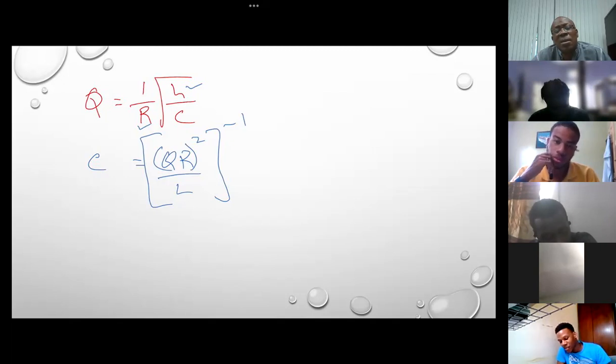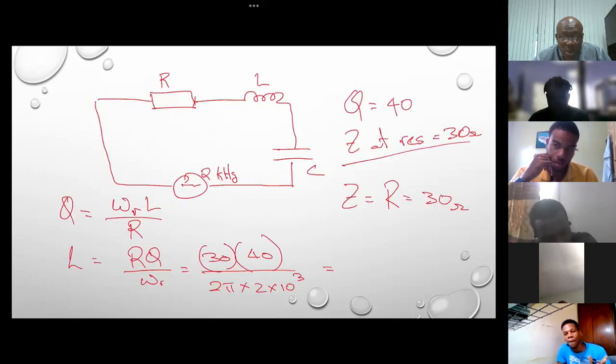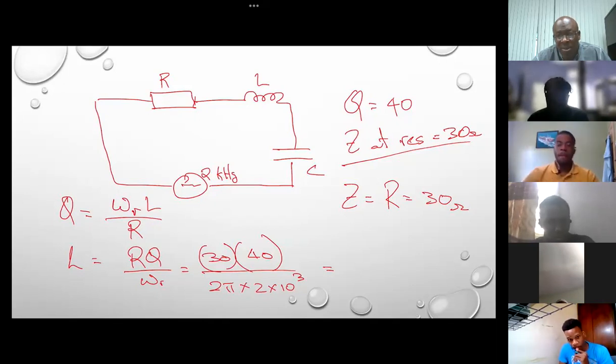For example, if they give us a value for a capacitor, we find the capacitive reactance, sir. We just found inductance, right, sir? So we can find the inductive reactance. And since inductive reactance and capacitive reactance are equal, we can just transpose 1 over 2 pi f C to find capacitance, sir.